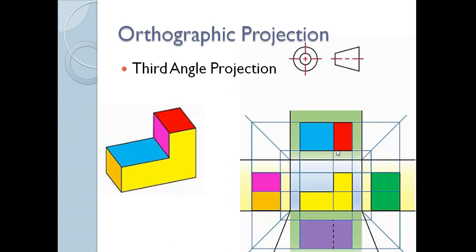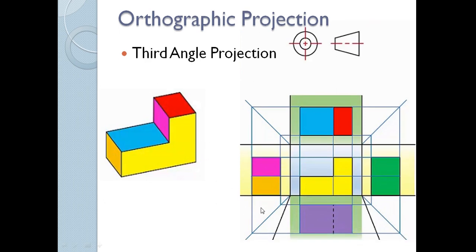In third angle projection, it is like opening out the views of the object. So the right end elevation stays on the right-hand side and the left end elevation stays on the left-hand side. The view with the purple as seen below is rarely used.